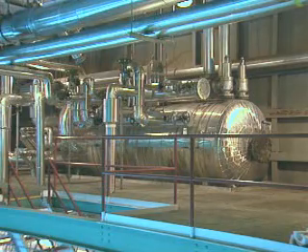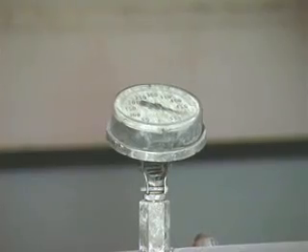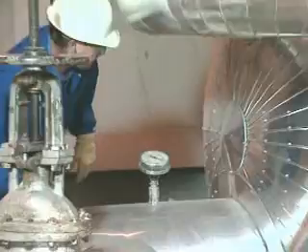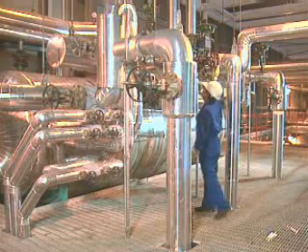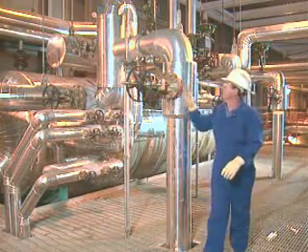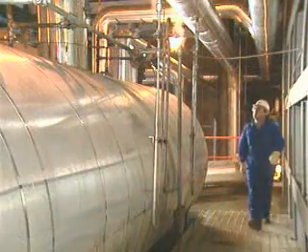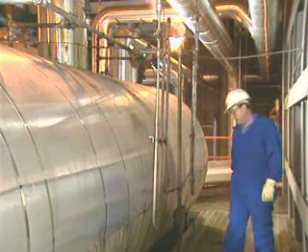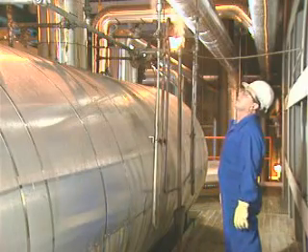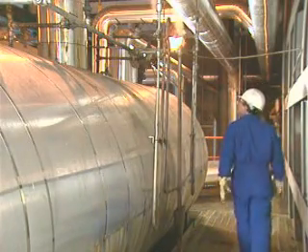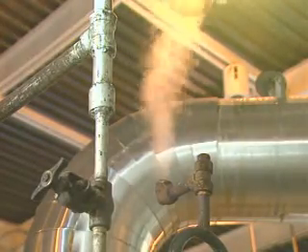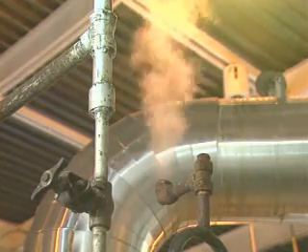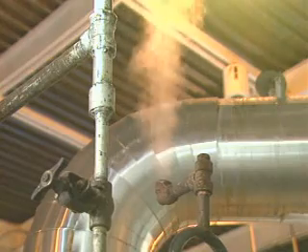Monitoring the performance of the deaerator is important for maintaining overall system and plant efficiency. Check the appropriate gauges for the proper extraction steam temperature and pressure. Look for any signs of leakage, and make sure that all the valves for the deaerator are in the proper positions. Watch for excess venting from the deaerator. That can cause a major loss of heat energy and fluid from the deaerator, which will decrease plant efficiency. Also watch for insufficient venting. That will allow oxygen and other gases to remain in the condensate and feedwater system and cause problems downstream.